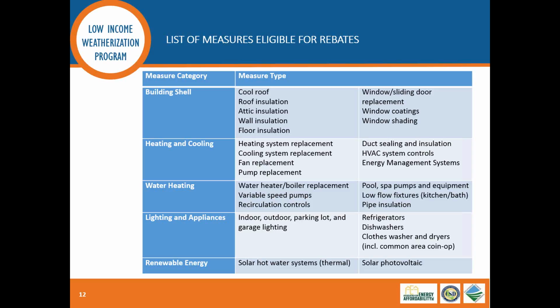We also, another area we'd be looking at is heating and cooling systems, and it can be as big as an actual replacement of an existing system with a new unit or a new central system, or there are opportunities as well to seal and test the ducts, to add controls to the HVAC system, or possibly even consider adding an energy management system if it's a larger building that has a more complicated operation. We can also replace pumps and fans depending on the type of system that's already installed. So it may not need to be a full system replacement, but rather some optimization of the current system.